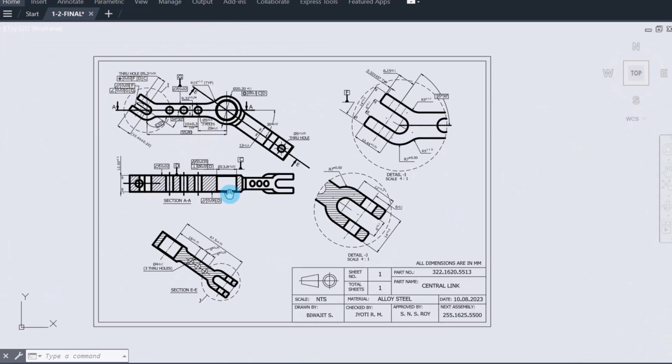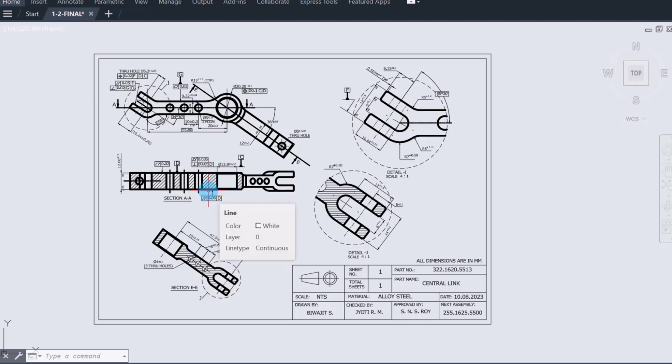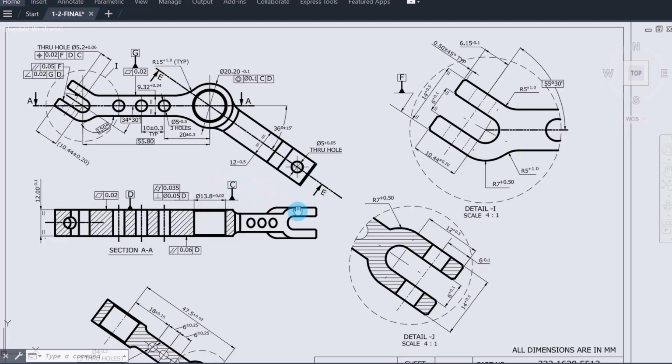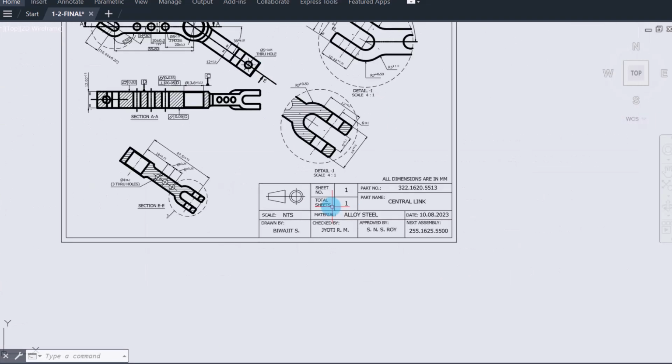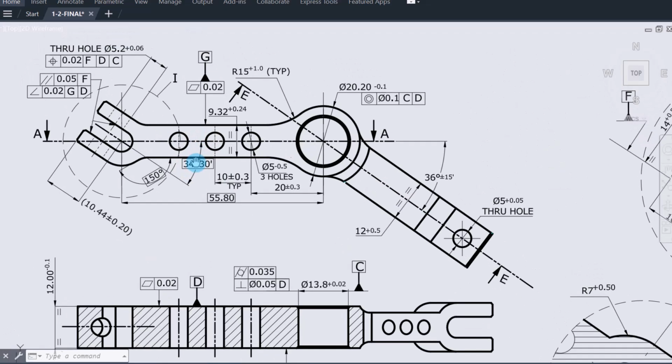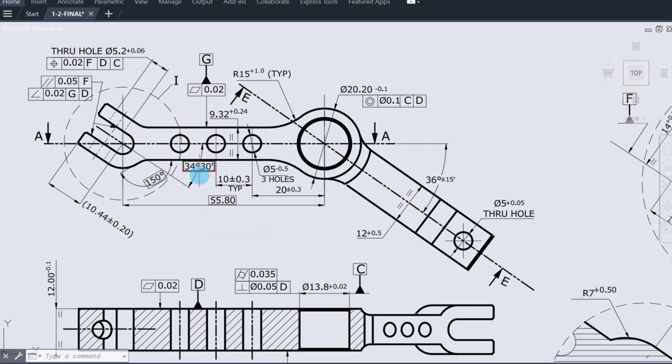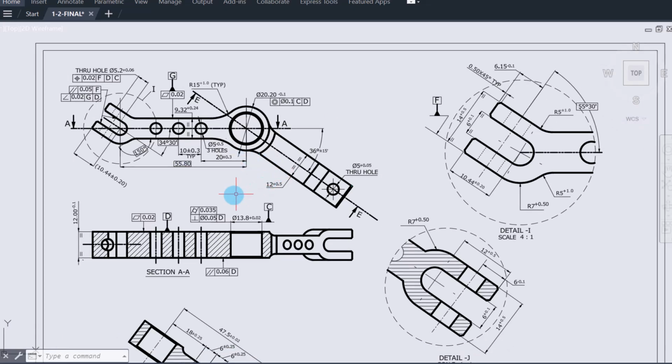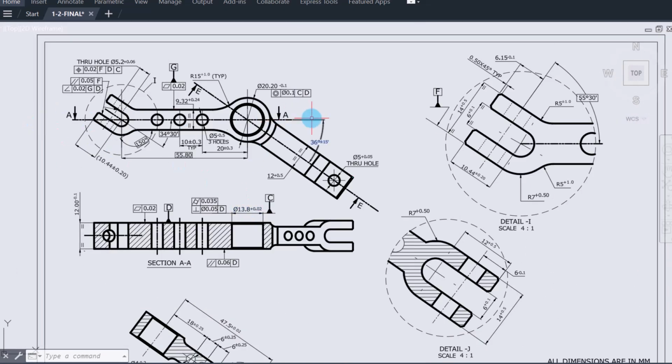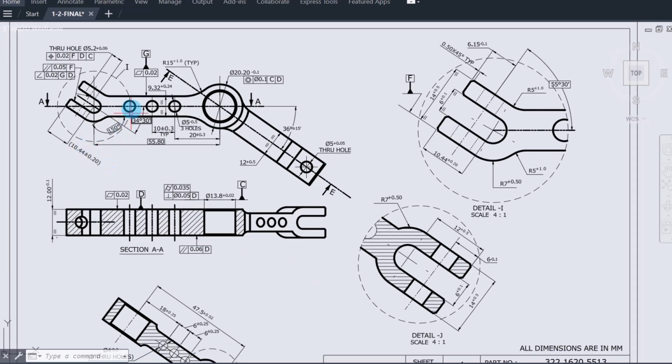Now look at this drawing one more time. A few minutes ago, it probably looked overwhelming, but now you know how professional engineers approach it. Start with the title block, then go to the main view and understand it, interpret the dimensions, study the holes, slots, read the section views, find the orientation of the section, understand the section views, find the detail views, and go to the detail view representation area, examine the details, and finally interpret the GD&T and datum references. That's exactly how experienced design engineers decode complex manufacturing drawings.